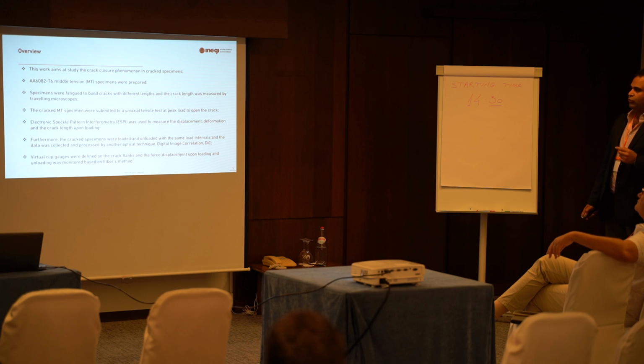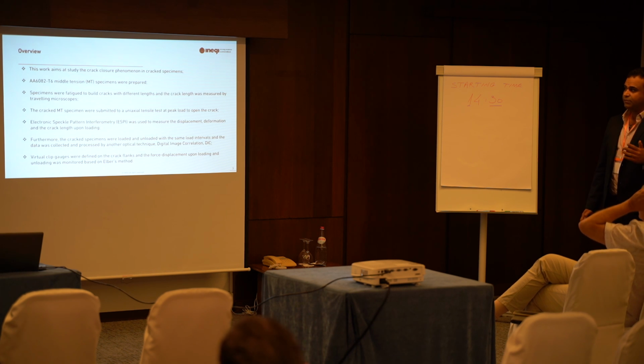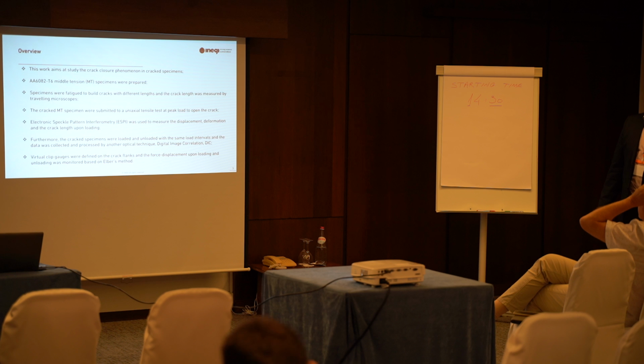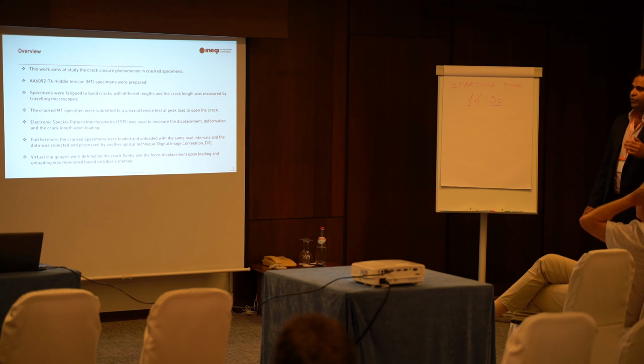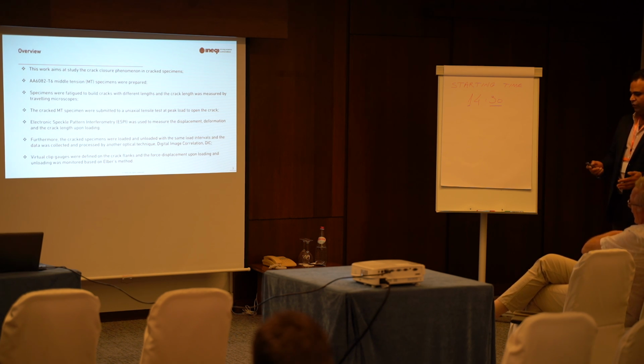So there are two different optical techniques, digital image correlation and ESPI, and I chose the MT specimen, the middle tension specimen, made of an aluminum alloy. There are several specimens with different crack lengths, but here I only present two of them, in order to show you the conditions under which we can watch the crack closure, or cannot watch it.